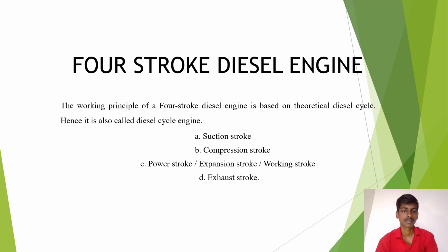Four-stroke diesel engine. The working principle of a four-stroke diesel engine is based on the theoretical diesel cycle, hence it is called the diesel cycle engine. The strokes are suction stroke, compression stroke, power stroke, and exhaust stroke, the same as the petrol engine. Here, the power stroke is also known as the expansion stroke and working stroke.